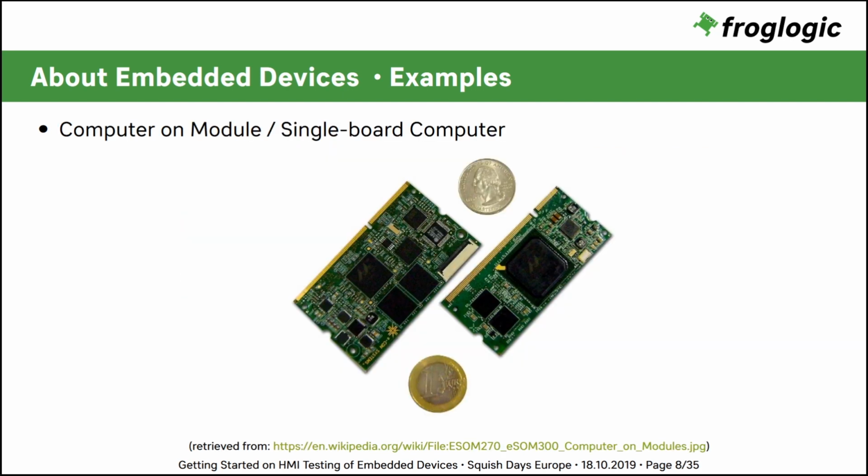Approximately 10 or 15 years ago we start seeing on the market little PCBs like these here, and they would have all components of a bigger computer on them. So for example here there is a CPU, then you have some RAM, and then there is some flash for permanent storage of the device. So for the first time people could run on these little boards full desktop systems like Linux or QNX, Windows CE and so on.